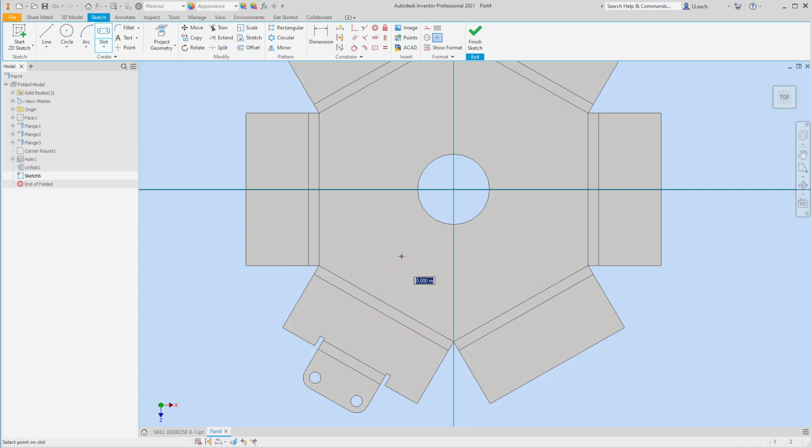I'm just going to make it crooked. I know it's crooked. I'm going to drag it out. So then, if you happen to do it all crazy like I did, I'm going to hit right click, hit OK. I'm going to make this line parallel with this edge. So if I click here, I can click this edge, click this edge. It straightens it all nice and neat for me.